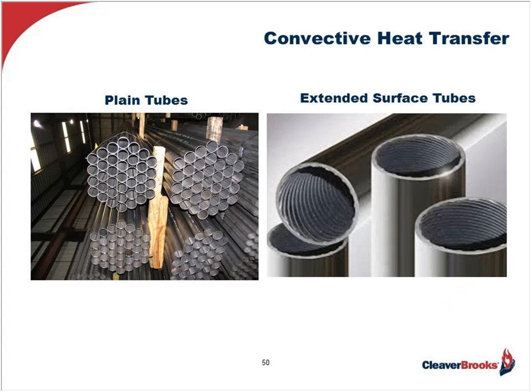Now, it used to be for many years, and it's still the case in many specifications in the market today, that you had to have 5 square feet of heating surface in the boiler in order to maximize efficiency and protract or extend the life of the pressure vessel. And quite frankly, with many designs out there today, it still holds. But times are changing, and customers are asking for smaller footprints, less weight without sacrificing efficiency. They don't want to sacrifice durability and long life.